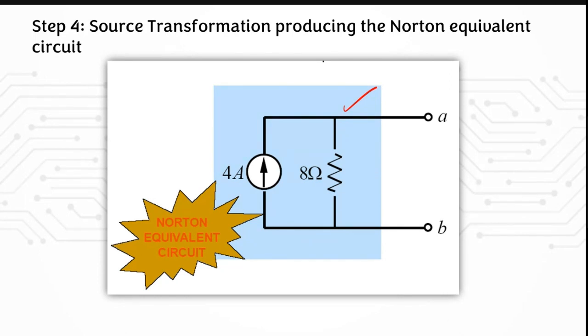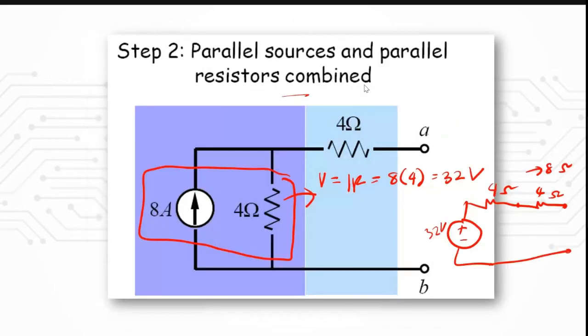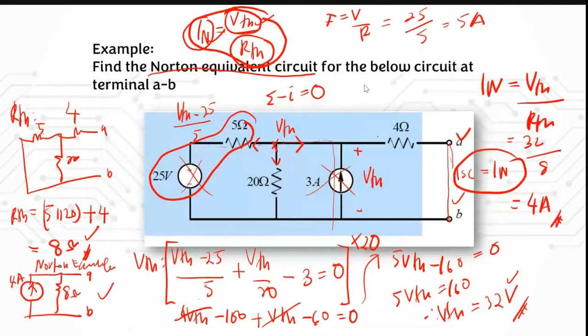This is just two methods that I show you, where you can just directly calculate using the node voltage as the first example here. Like this example, I'm using the node voltage so that you can just directly calculate for IN, where IN is equal to Thevenin voltage over the Thevenin resistance directly, where the first thing you need to calculate is you need to get these two values, VTH and RTH, so then you can get IN.